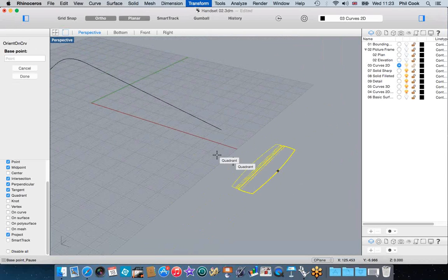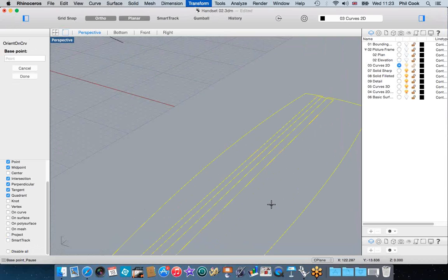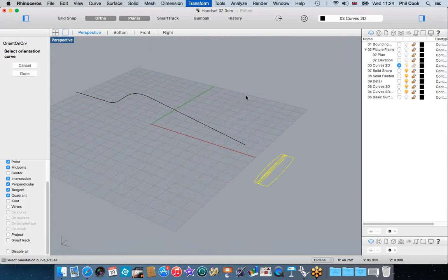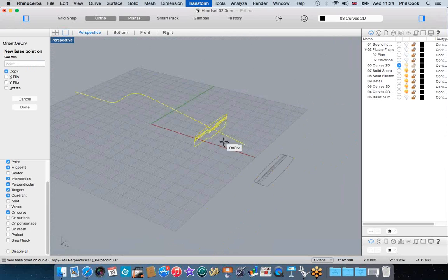And if you remember when we set out this side curve here, this side profile curve here, this was the top of the lower split line. So I can just snap to the midpoint of that and then snap to this point here, and you'll see how this command aligns the curve perpendicular to my rail, if you like.